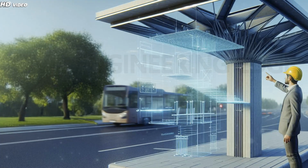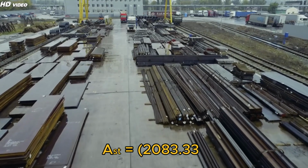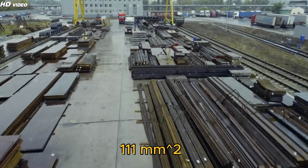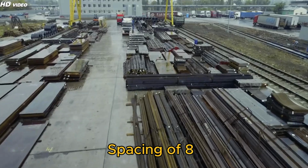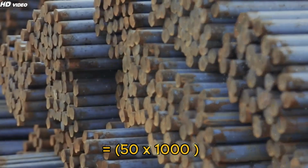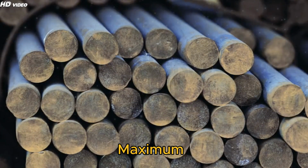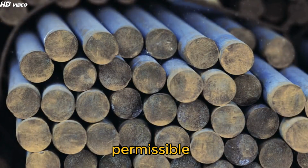Area of steel Ast equals 2083.33 x 1000 over 230 x 0.90 x 81 equals 111 millimeters squared. Spacing equals 450 millimeters.